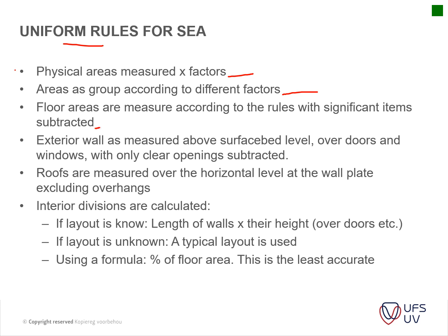Exterior walls are measured above surface level, over doors and windows, and only clear openings are subtracted. So the rule of thumb is you measure your walls over the doors and windows, except if it's a substantial opening.